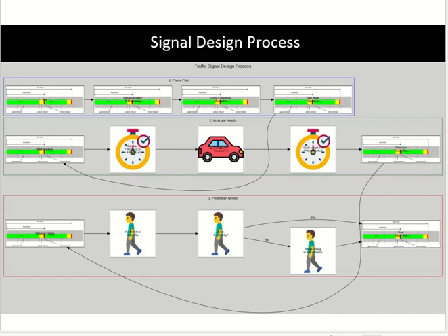And usually the pedestrian timing, because you can have a phase for left turning, right? Okay? So I am the pedestrian and I have to cross. And there is a green signal here. And this green signal could be for straight, could be for left. So which timing will you check for this pedestrian? Usually the straight one. The straight time.